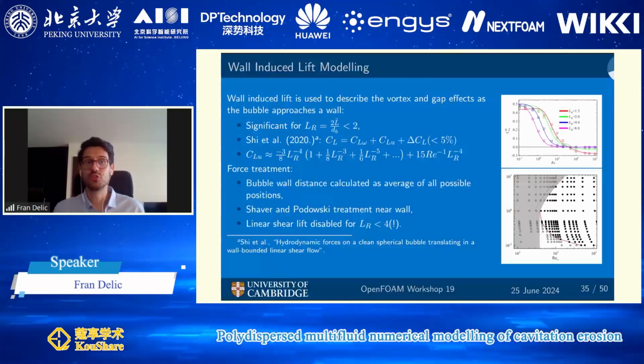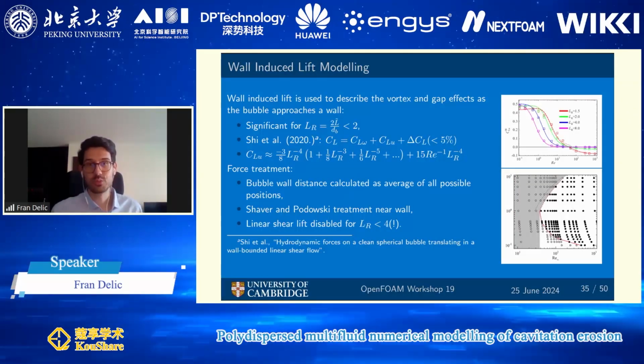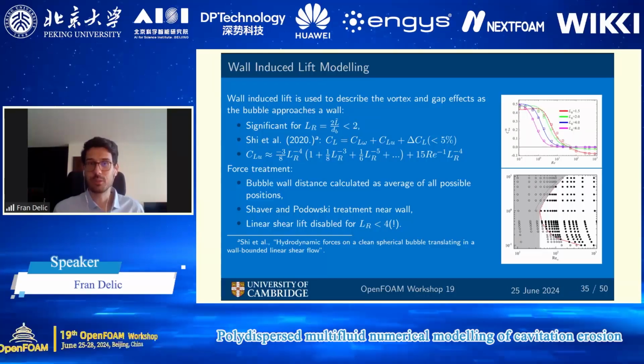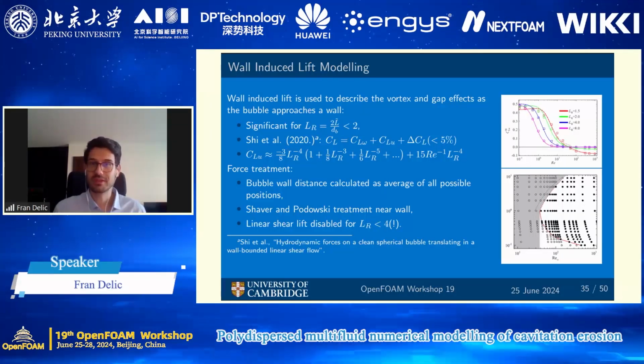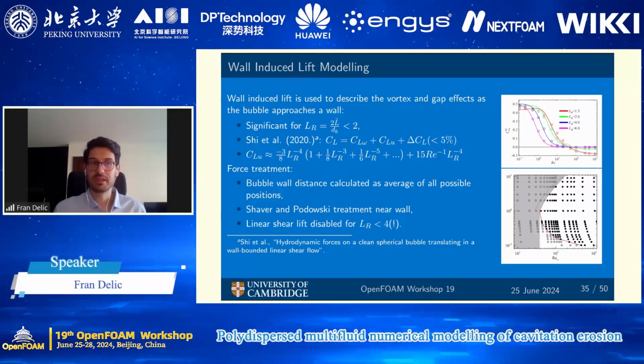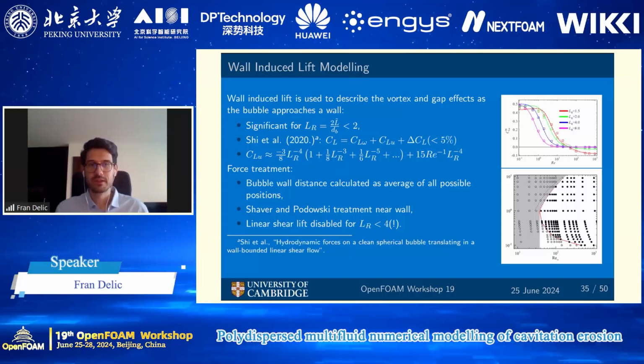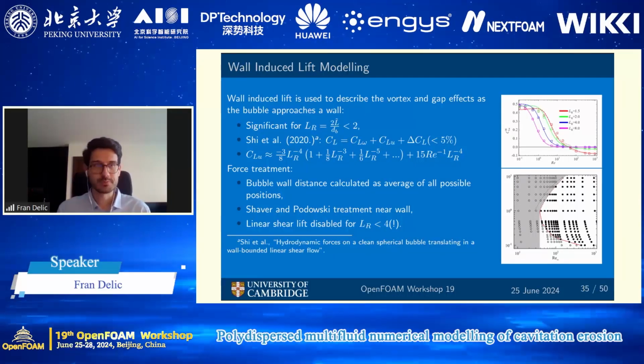So this is due to wall-induced lift, which is a term used to describe the complex interaction of vortexes and gap effects as the bubble approaches the wall. And it's significant for a dimensionless distance of less than 2.